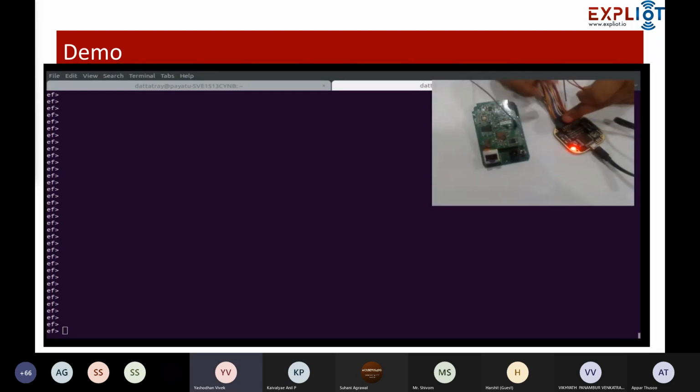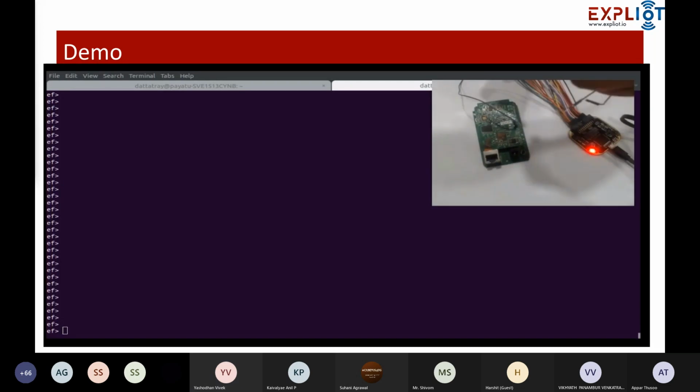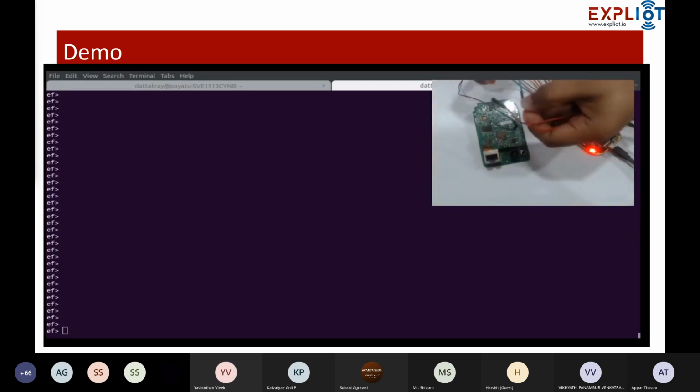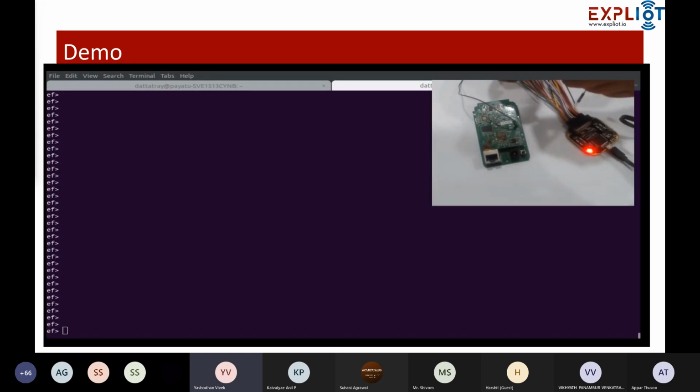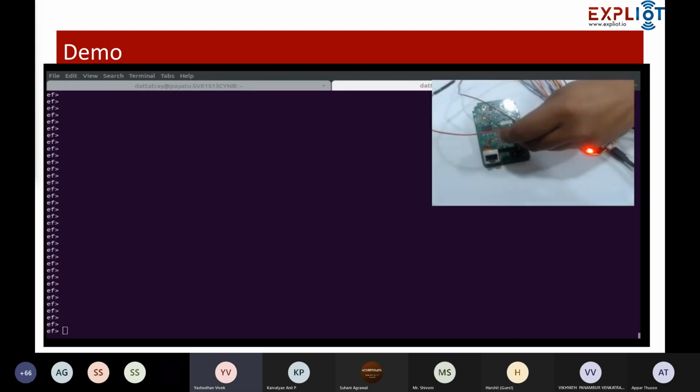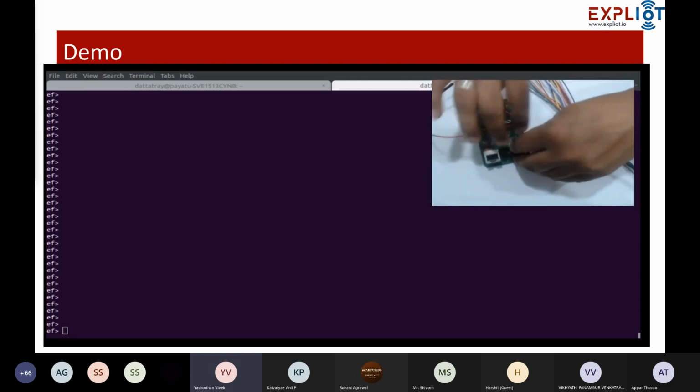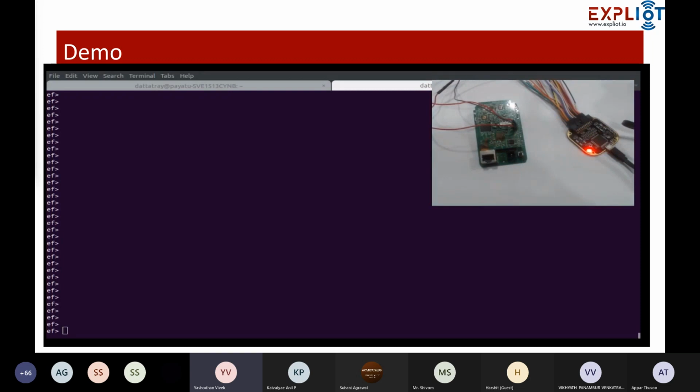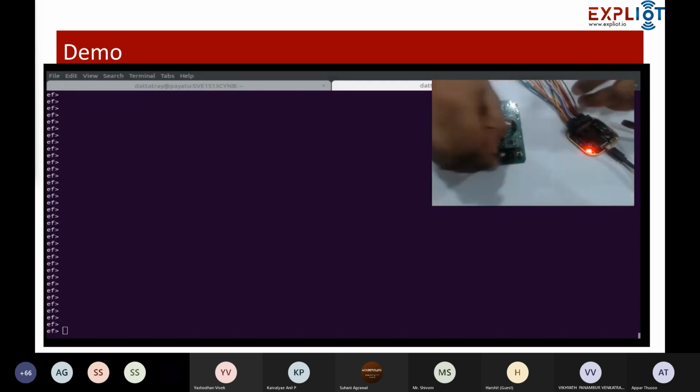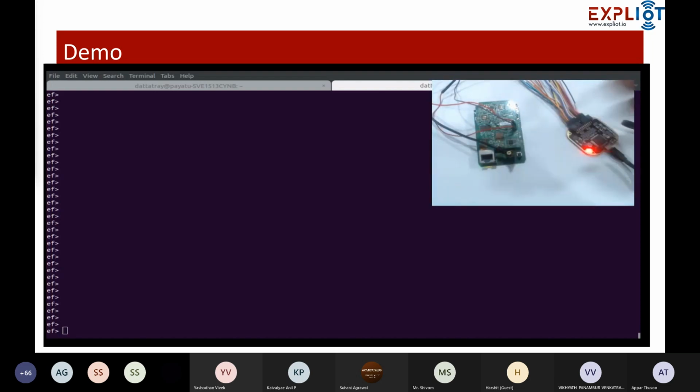Now the next part is we have the rest of the 3 pins. We are basically interested in the receive and transmit pins. So let's connect any two random pins from this bus auditor to the rest of the pins. And now what we'll do is power up the camera and try accessing this bus auditor that has been connected.